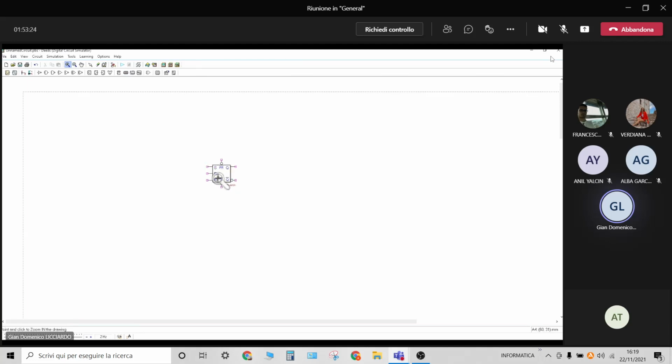Here we have an enable, a preset, and a clear that are active low, Q, not Q, S and R. I want to use a D. It is much easier to understand. Now, first of all, I want to disable preset and clear, so they must both be put at 1, at a constant value.